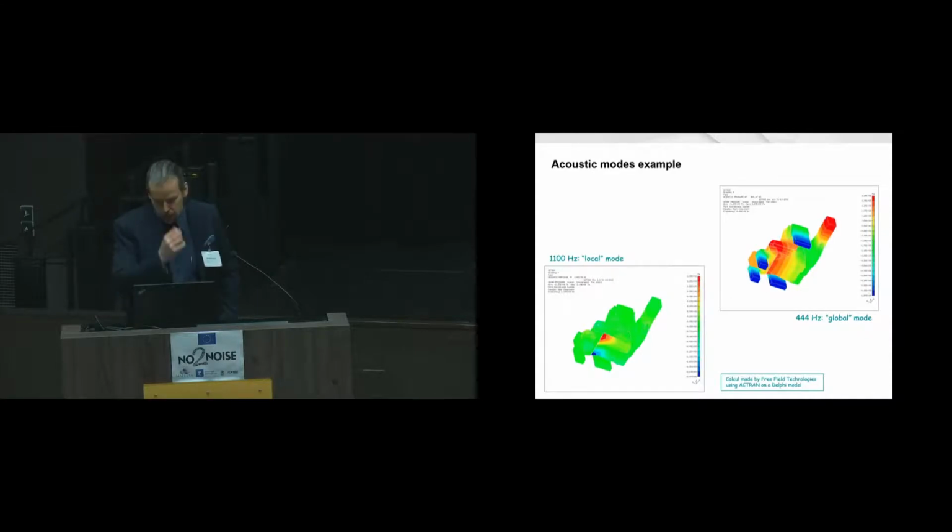Just a simple example for acoustic cavity, the eigenmodes are well known. Maybe something to mention is that when you increase frequency, the modes become much more shaky and sometimes local, and you cannot really identify them from an experimental modal extraction. You have too much variability, and so those modes are still useful for numerical speed-up of your simulation, but as help for understanding the system behavior, they are not so useful anymore.